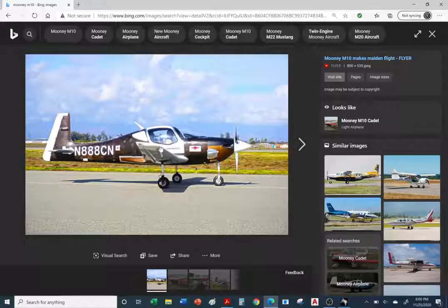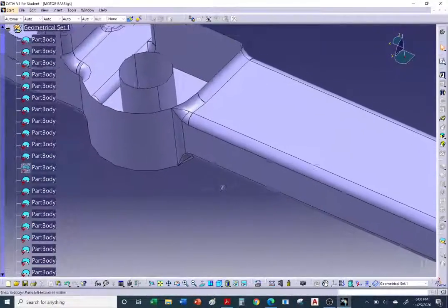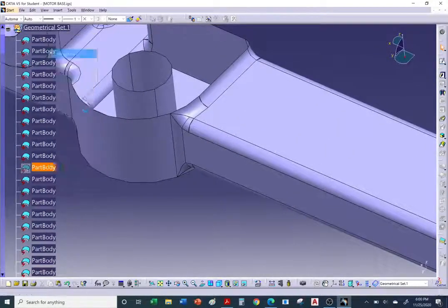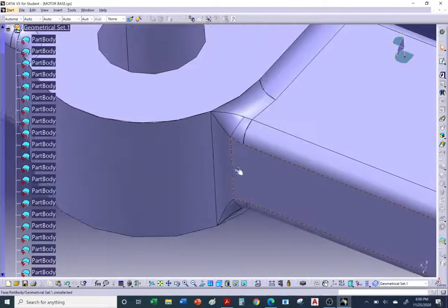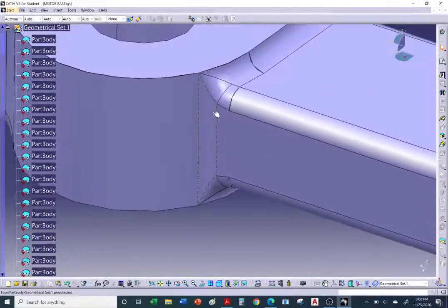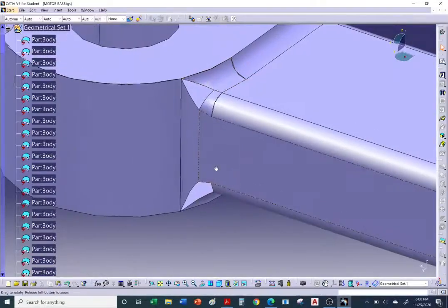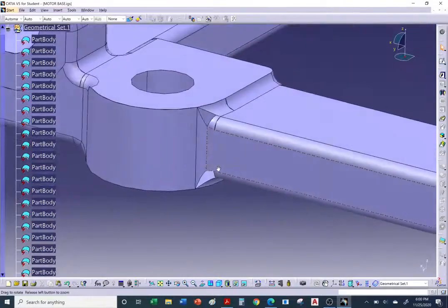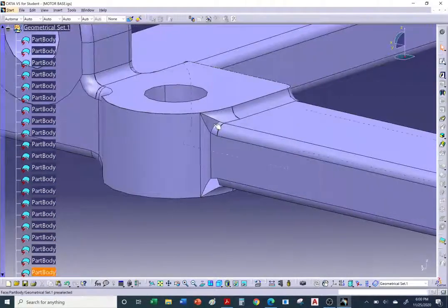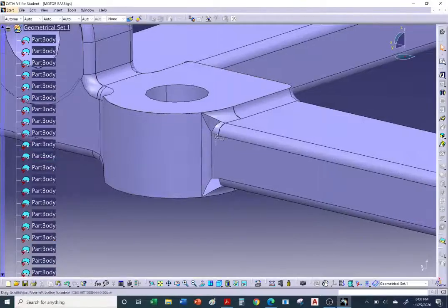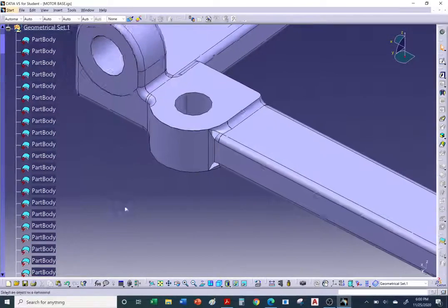And we would have a lot of trouble getting these fillets here to translate over. So one of the issues we would find is, let me go back and unhide this one. When you would translate this to an IGES, sometimes it would be patches missing, and it would typically be at the fillets. You would see things like this, just missing. Okay, I want you to be aware of that. It's a big issue, especially with fillets that are tapering and turning or twisting. And you would have to go in there and fix it. Or maybe change your settings for translating your IGES and step files.